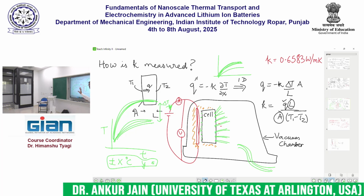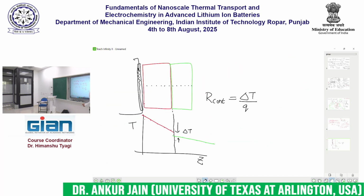Even if I am only interested in measuring the thermal conductivity of the cell, I will probably want to have an arrangement like this, where this is my cell and this is some other standard material, perhaps quartz. Why? Because the thermal conductivity of the quartz is well known.